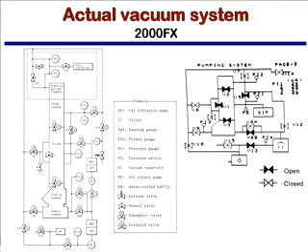But what's nice is that this thing updates itself continuously on the microscope, and it's actually a bit simplified over here. So again, if you were to turn the thing on, all of the valves would be closed. The first thing that would go is your roughing pump, shown at the bottom with a little hole there, would turn on, and you would start to evacuate the main column through valve, say, V9. Okay? And then you would turn on the oil pump, the diffusion pump, first back that out, and then use those. It's only showing one diffusion pump, even though there are in fact two, and use those to do the primary pumping down there.